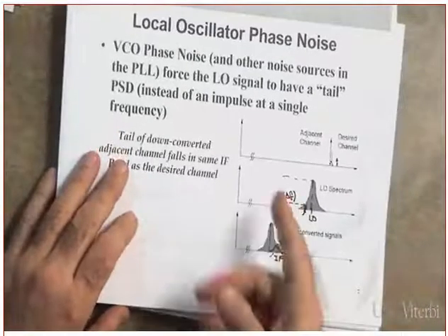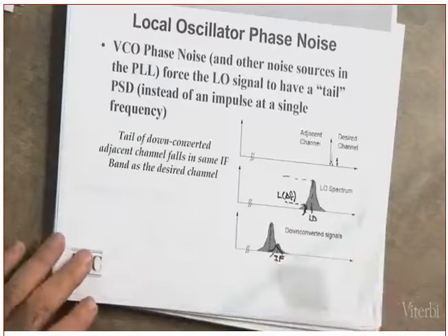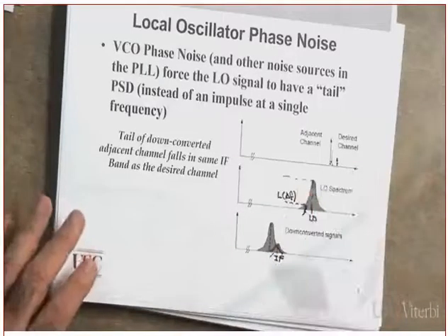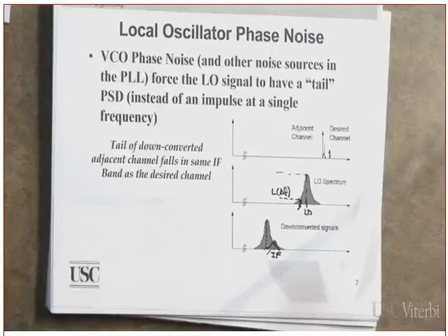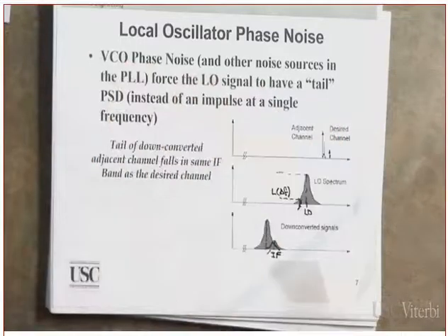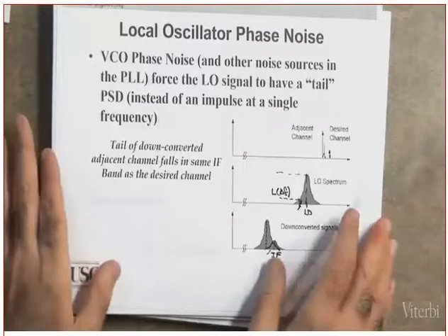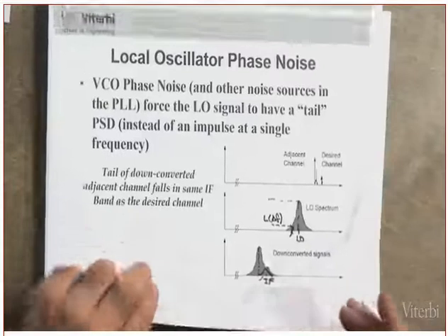What is another problem of this that we saw earlier? In the mixer. Remember in the mixer when I told you that if your oscillator is a square wave, it will generate all types of harmonics. And if this one is mixed with the desired signal, the noise will begin to fold. Remember the folding? It results in an increase of the noise floor. That's what we meant by saying that it will affect both the sensitivity and the selectivity. Clear? Okay, good.